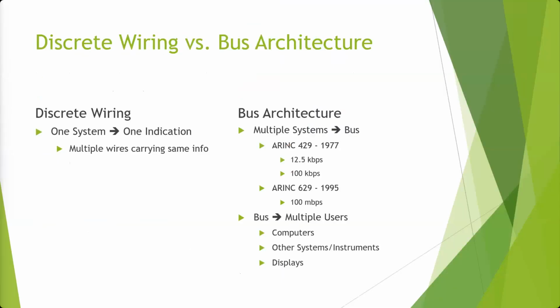Say not only is this an output, but then it's got a button on it, right? It's a light that's also a push button, right? That push button could send data back to the bus, and that data may then go to gauge number 2, output number 2 or something, right? So we go to a bus architecture where everything on the bus is available to everything else. Not everything's going to use every bit of data that's on there, but it's available if we want to pull it in somewhere. So it makes reconfiguration more possible. It allows us to have data in more places.